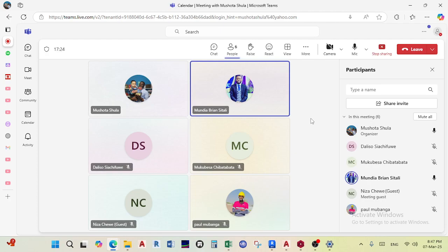Where they have stopped, that's a construction joint. Now, the fact that they leave a 10 millimeter space, that's to allow for expansion. That's an expansion joint. So you find that the same space can be called a construction joint and can be called an expansion joint, but the meanings are different. Construction joint is to phase your works. Expansion joint is to allow for one part of the building to be able to expand and contract without affecting the other part of the building.